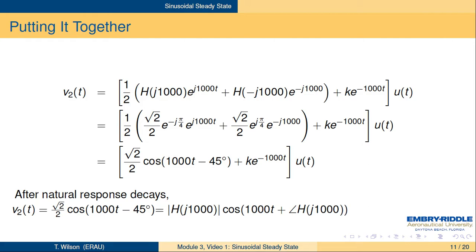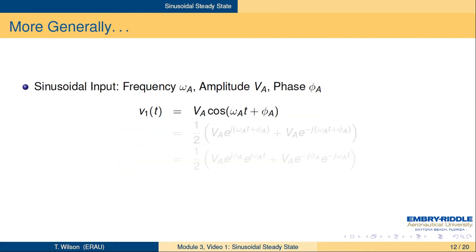So this derivation we've done here, and what we're going to do for the more general case, is not how you solve these problems. You don't want to go through and do this every time. We're doing this to derive the principle and to show what the principle is. But then we'll have a couple of examples here that just show you how you apply it. It's pretty simple. You plug in j omega for s.